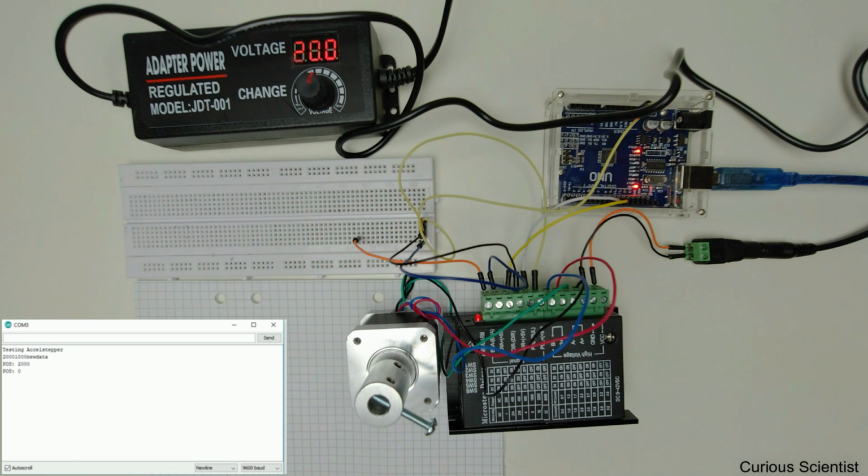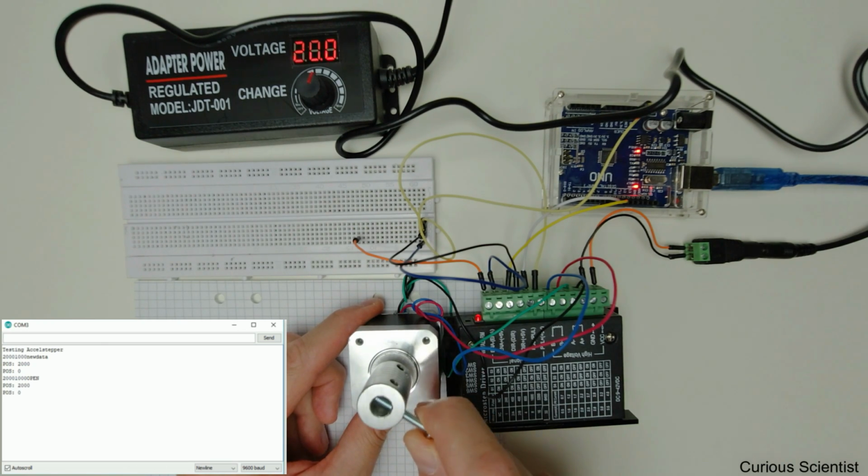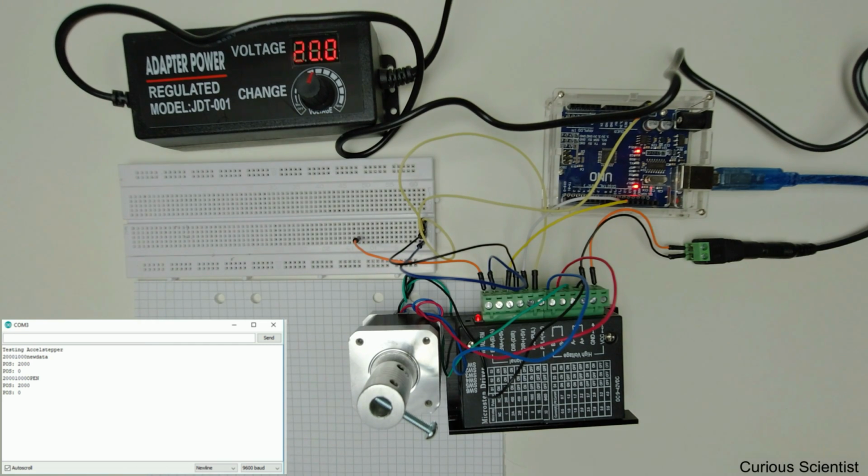So now I know that the O command, the open, does the same, but let's see. So O, 2000 and 1000, so 2000 steps and 1000 steps per second. So let's start it. 5 rounds or 5 revolutions. So this is it. And if I do the same with C, that's the close command for my code, that is the other direction.